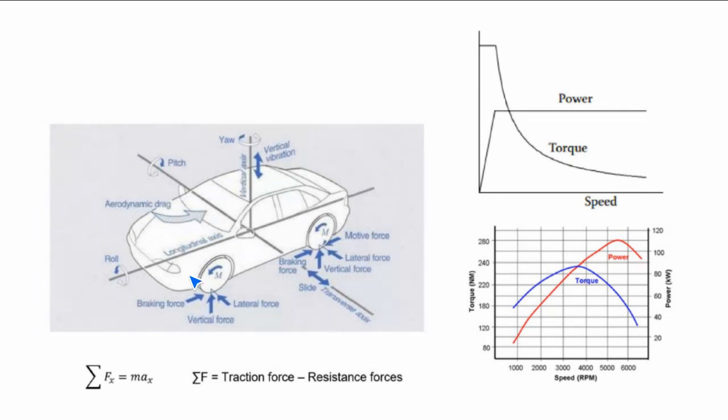For example, maybe two days ago, one student in your class asked me, we don't know the wind turbine speed, wind speed. Actually, you need to calculate torque demand in this application. How can you calculate the torque demands? Firstly, you need to know blade length, wind force, drag coefficient force, also blade material, etc. Firstly, we are starting with the force calculation. Okay, this is very important.